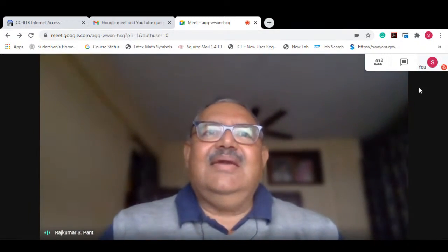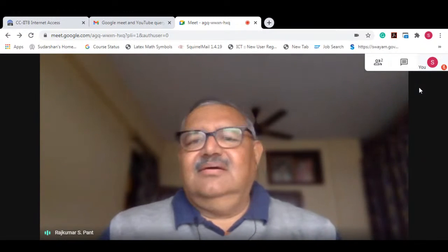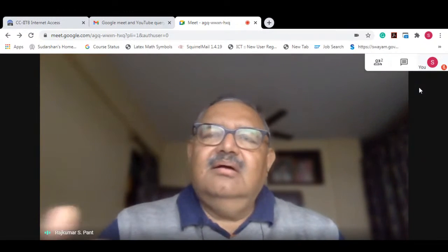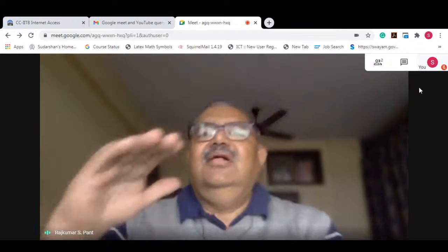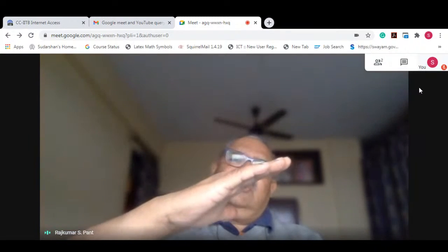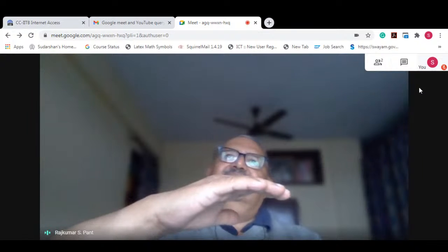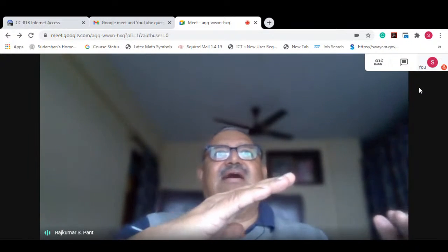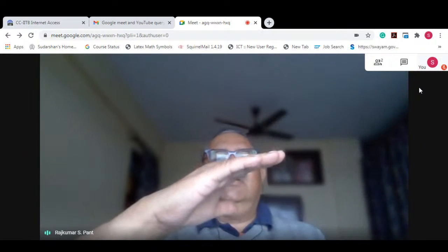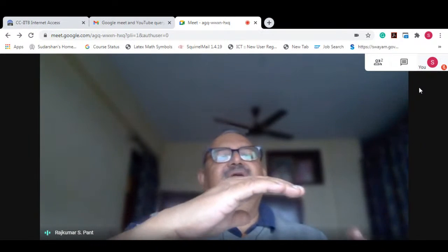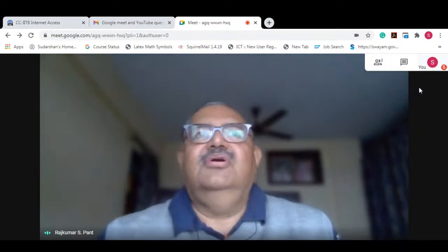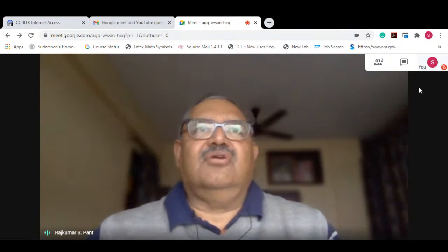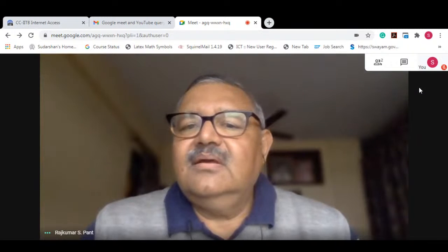When you give a larger camber, then you get much better performance at high angle of attack, because if the nose is drooped, otherwise the air will have a very large area to climb. But if the leading edge is drooped, then you give a rounded area for it to climb. So you avoid the separation and stall at high angles of attack.